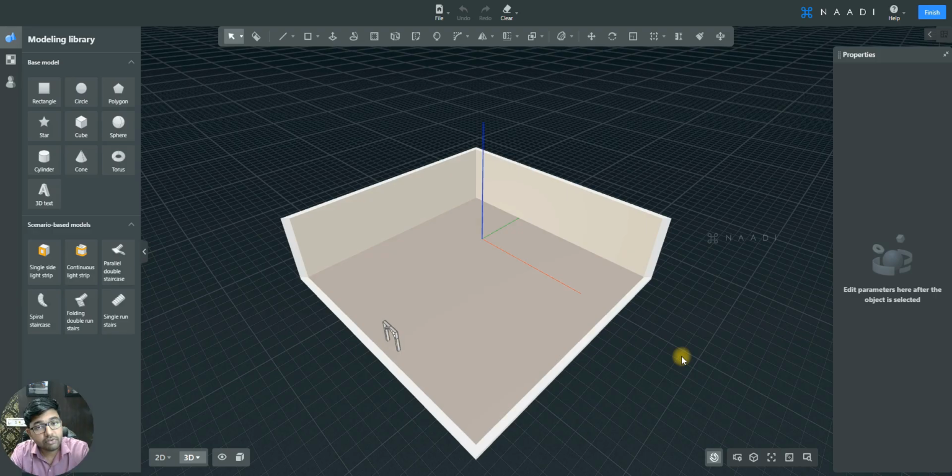See, in our previous section, we talked in detail about your custom modeling basics, right? How we can create a component from scratch using custom modeling. And in our last section, we talked about how we can apply a finish for those custom models. So in this session, we'll be utilizing both, and I'll be showing you how you can create a custom swing and sliding door based on your design requirement.